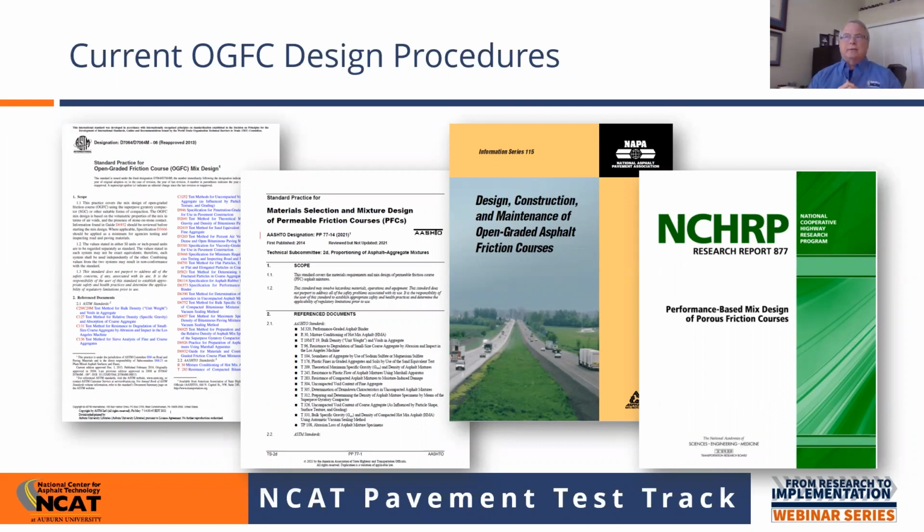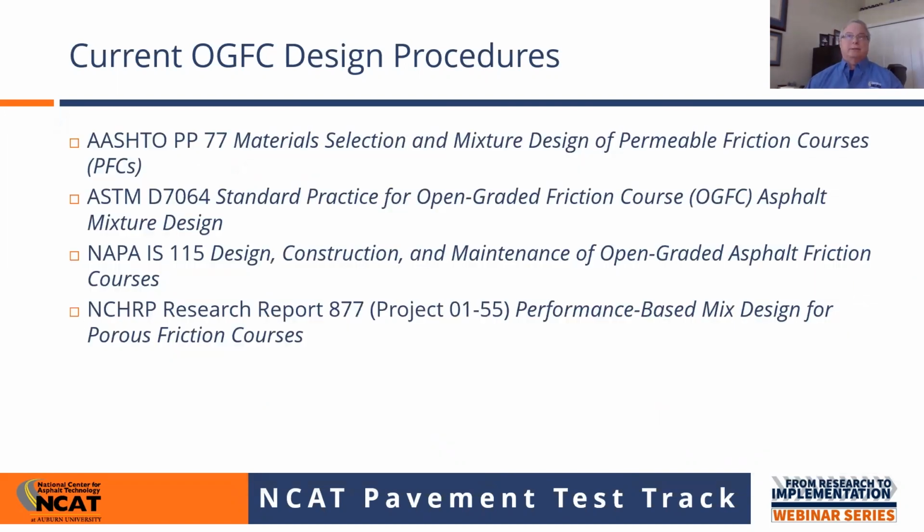And then most recently, there was another report done as part of an NCHRP project that really looked at the best way to design and maintain porous friction courses or open graded friction courses. So again, these are those same design procedures that we discussed previously. The NCHRP Research Report 877, from project 1-55, and I think Dr. Nam Tran from NCAT was the PI on that particular project.